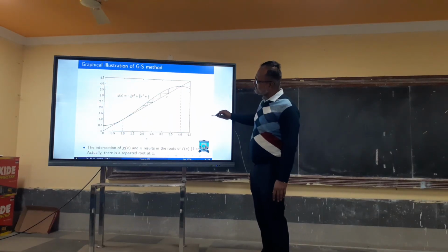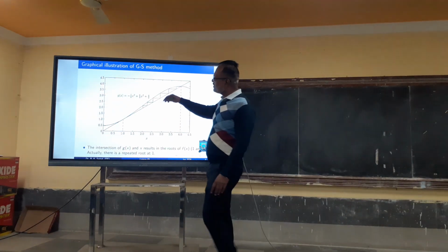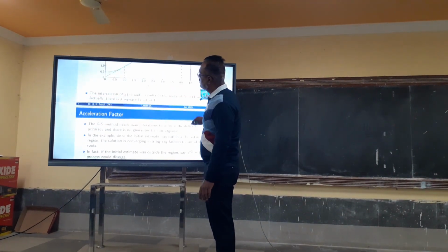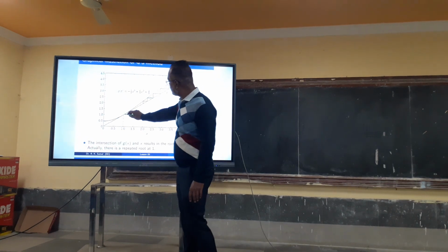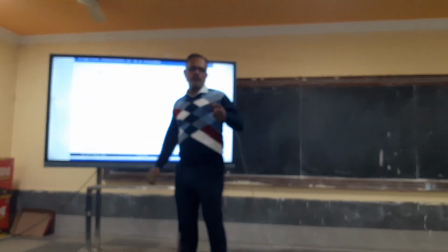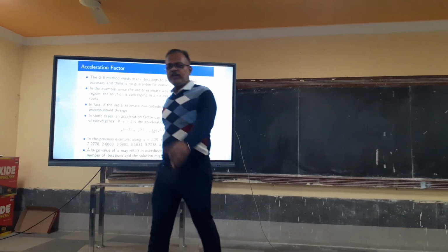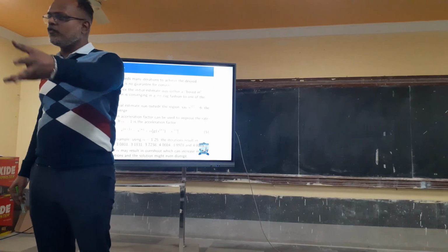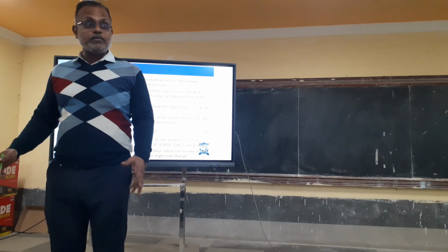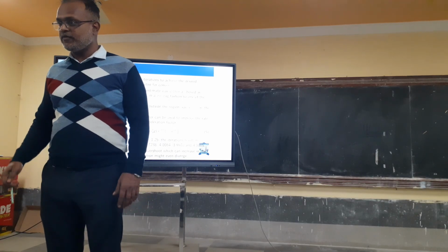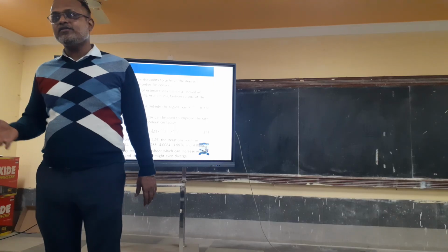Now this I have taken from Hadi Saadat's book. How the convergence happens is not important, only for reference as given here, how we are converging. As you see here, you can have different solutions. Here one solution, here another solution, as you said. We can have different solutions, but it depends on feasibility, depending on the context. For example, voltage, you get the result 1.05 per unit. Accept. Now suppose in the load flow solution you get a voltage of 5 per unit. That is 5 times the rated value. It's not a feasible solution, so you reject that.